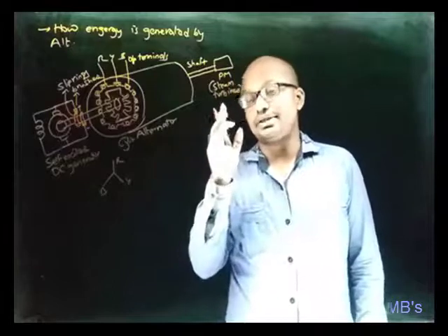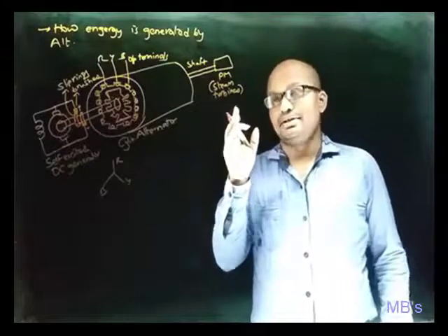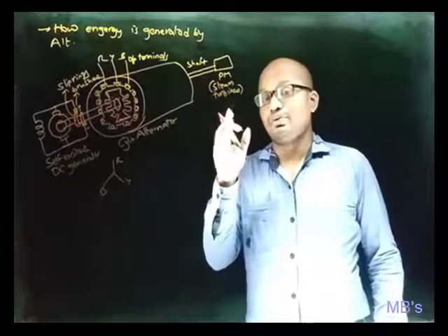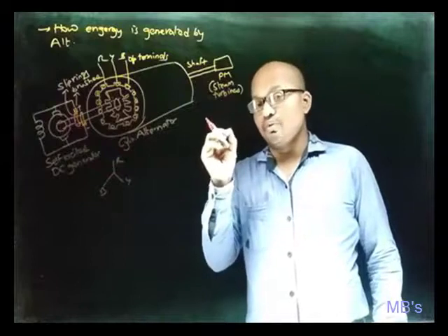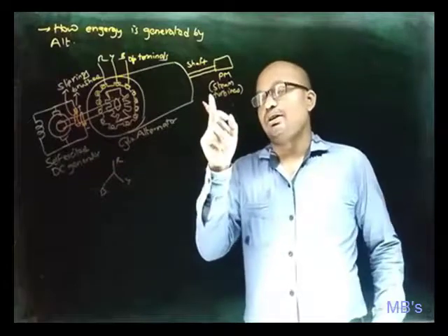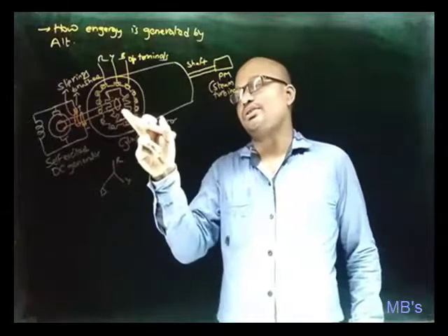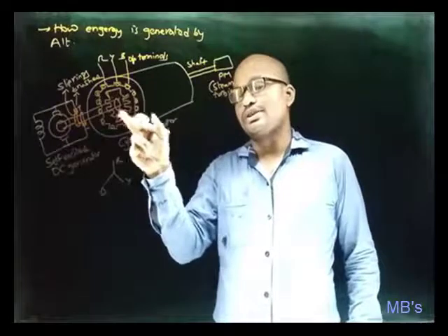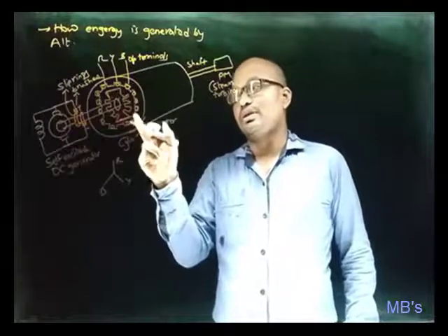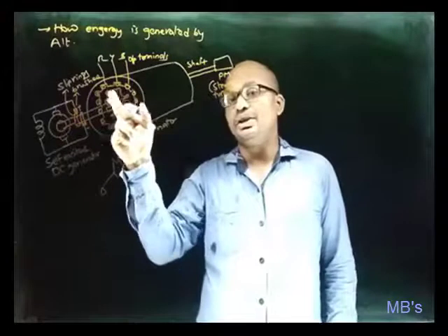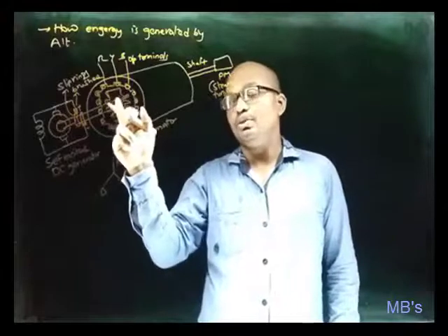With the help of this steam jet, the turbine blades in the prime mover will rotate at the speed governed by the speed governor, and as the shaft is connected to the rotor, the rotor also rotates at the speed maintained by the speed governor. But here there will be no rotating magnetic field created because poles are not created.